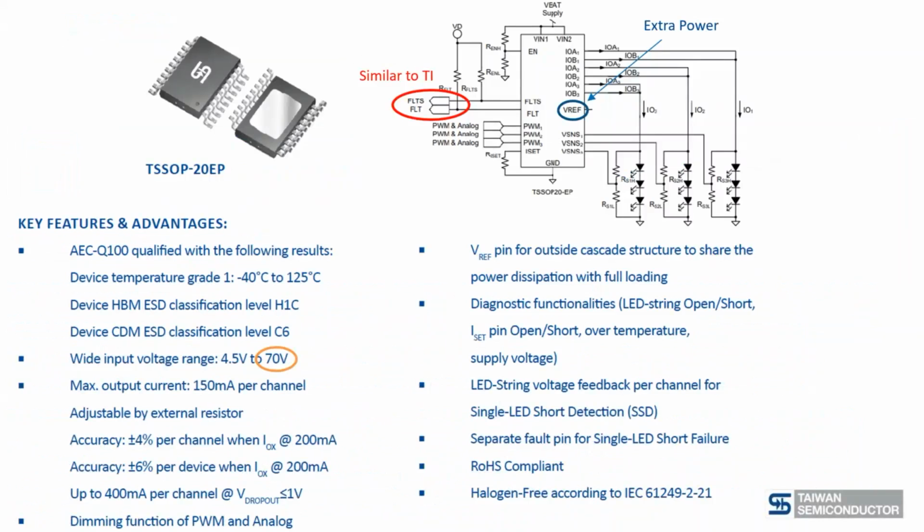One slide overview here. I put some things here which are typical for the device, or where it differs a little bit. If you look at the schematic, on the top side there are two current sources driving 3 LED strings in parallel. That's what the 6 pins on the top right-hand side of the IC pin out are doing.